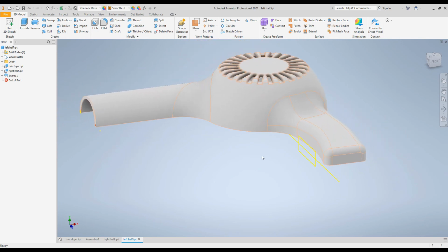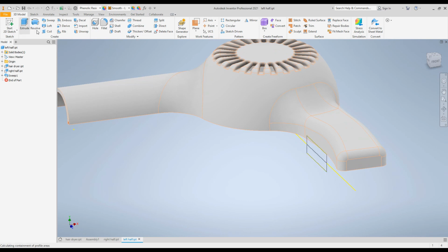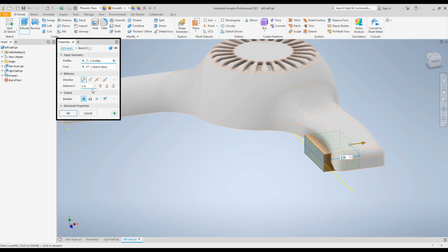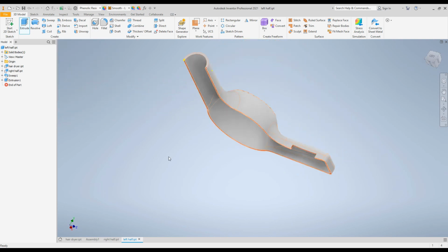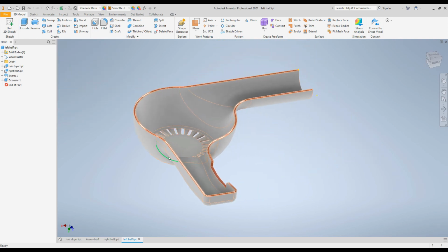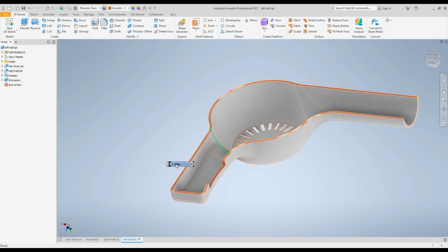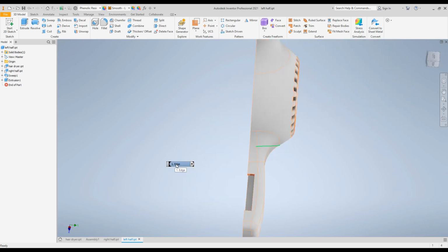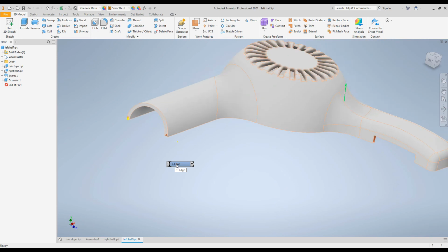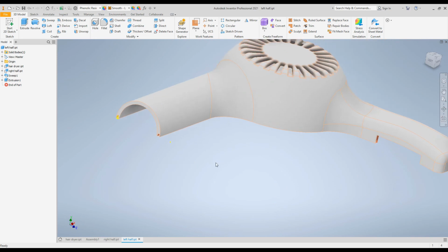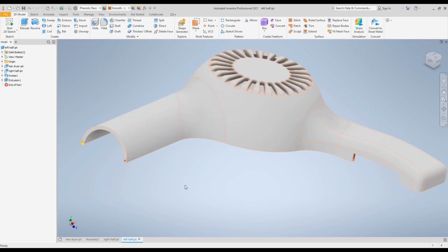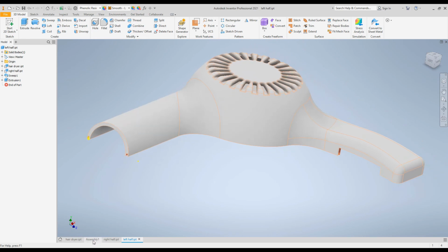And so you can see now in the left half I've got that sketch also. I can extrude it, subtract it, and you can see I'm starting to get some details on this part. Okay, so anytime you want to derive something between the two halves, you can either use it directly like we just did for that hole, or you can use it to constrain some more features, more sketches that you've got to draw in this half so that they're related to each other. You can use the derive command to do that.